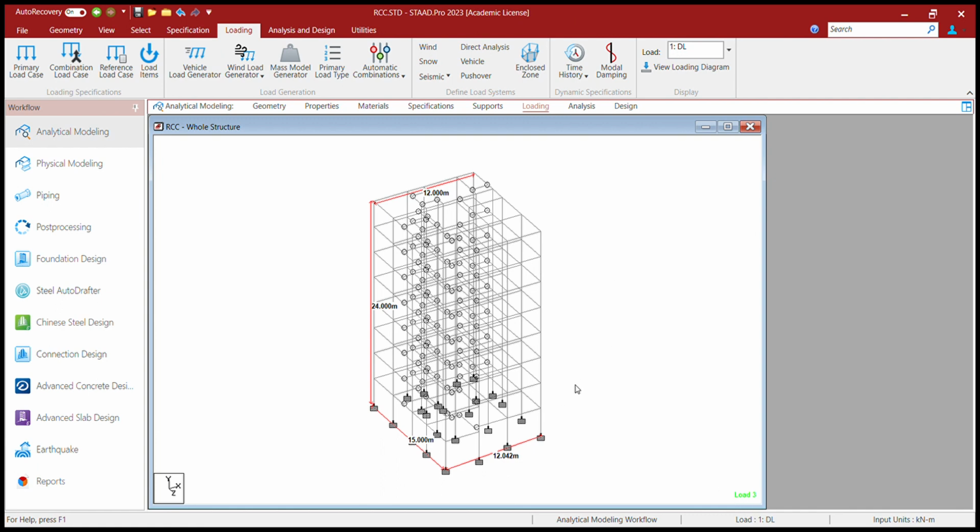Click on OK. We need to define the other parameters for rectangular building. All dimensions it has taken already. OK. Add. Exposure factor, right now assume 1. Add, close. Assign this exposure factor, assign to view, and yes. Okay, so wind intensity is created. Now we'll apply it in this load, wind load.